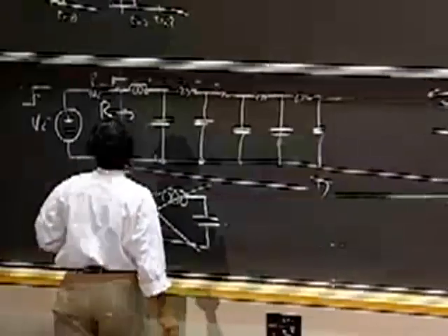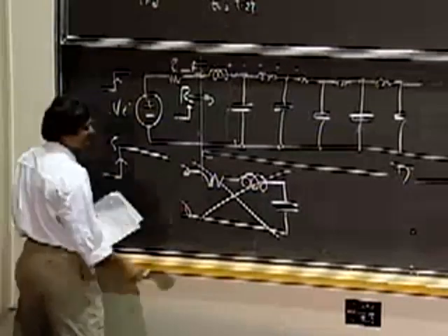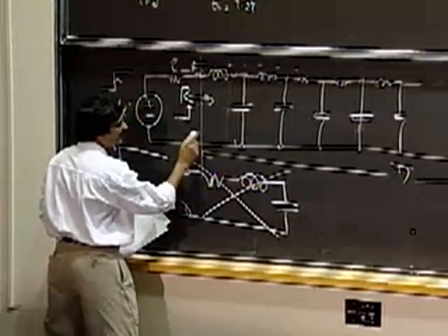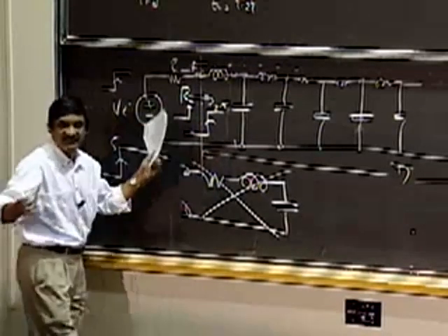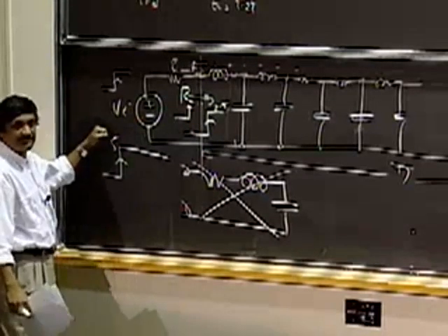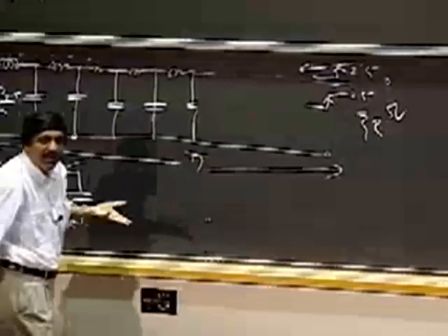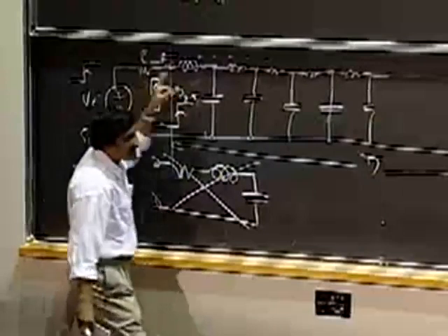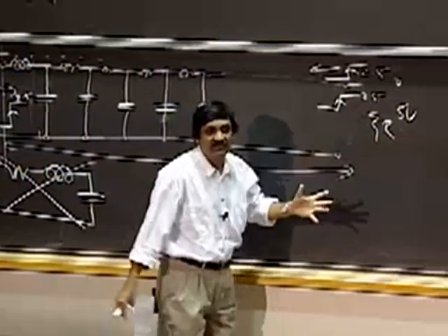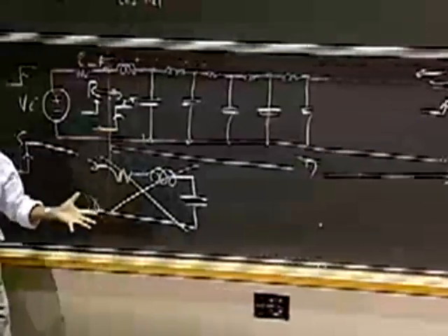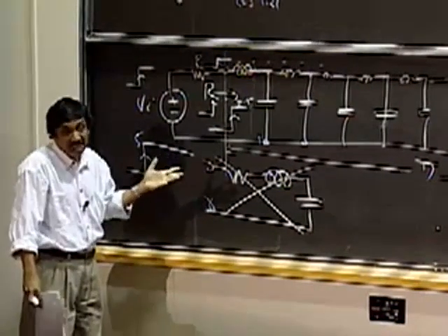So what I'm going to find then is that out here, this goes up to 5 volts, but out here, I will have a signal that starts out and goes up to 2.5, and that's it. I lift it up, goes down, goes to 2.5. Because in the lumped model that you've been dealing with, it's a resistor R to ground, and so it's your standard lumped model, a resistive voltage divider, and it should simply work. Well, let's see.